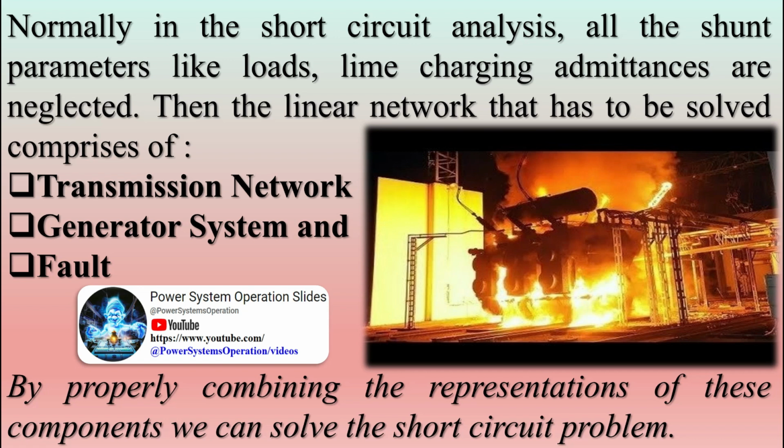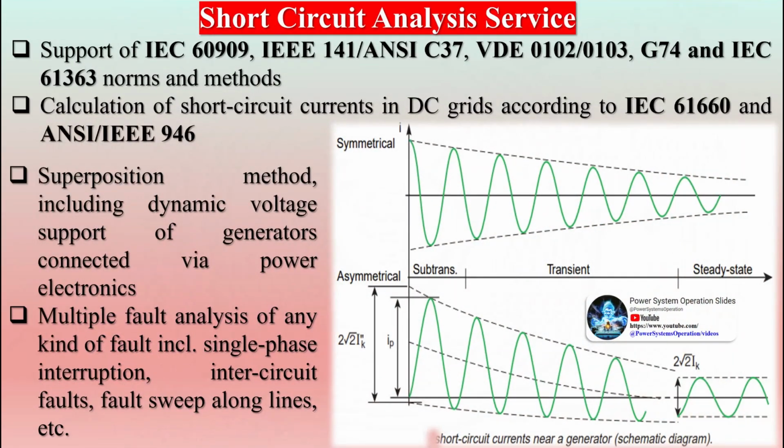What are bolted, arcing and ground faults? A bolted fault typically results from a manufacturing or assembly error that results in 2 conductors of different voltages being bolted together, or a source of power being directly connected, bolted, to ground. Since the connectors are solidly bolted together and no arc is created, the high current quickly trips a protective device, limiting the damage. An arc fault is one in which the short circuit creates an arc.